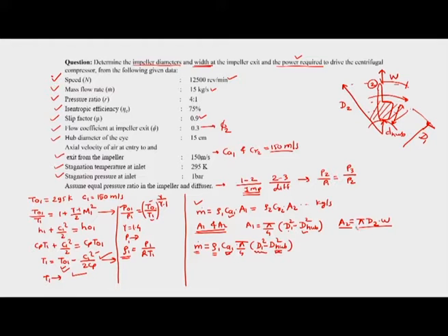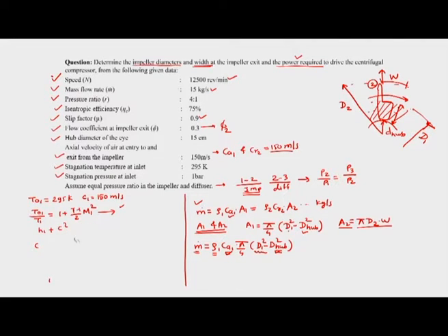So now we know the formula that we have, basically mass flow rate is equal to rho 2 into A2 into U2 or C2 or CR2. This is the mass flow rate formula. Basically U means velocity. We have to keep some velocity which is normal to the area at the outlet, and for normal to the area at the outlet we have CR2 velocity.